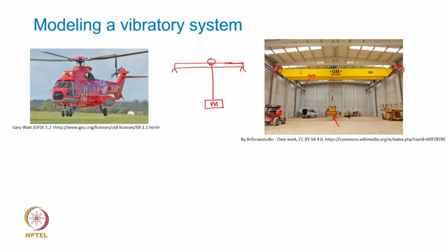If we assume that the pulley structure, which lifts and lowers the weight, has comparatively less mass as compared to the mass being lifted, then I may like to model this entire system as a single degree of freedom system. Okay. Now, how do I model this as a single degree of freedom system? The wire rope here can itself act like a spring, because the wire is not absolutely rigid, and under the action of such a heavy load it can stretch, and that stretching means that it is a compliant member and may have certain stiffness.